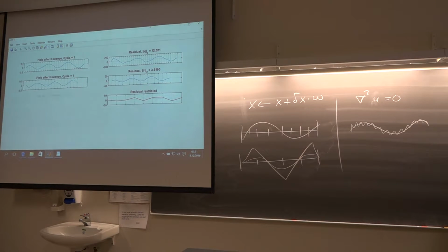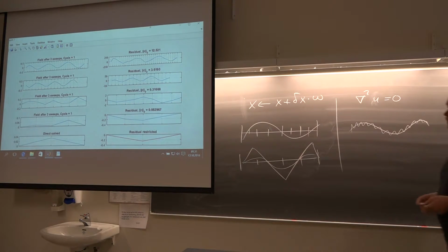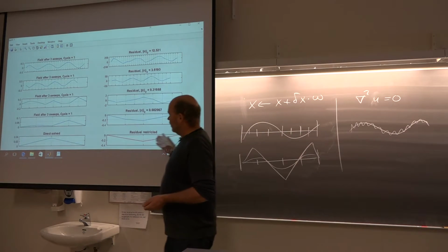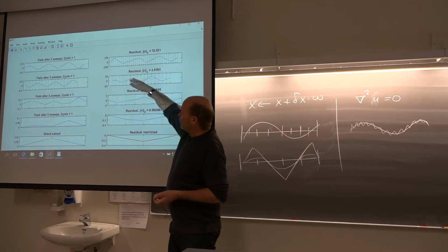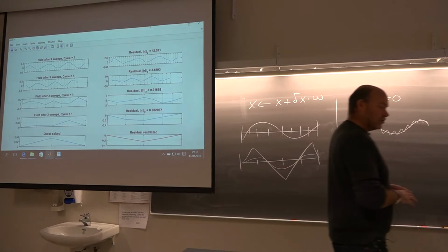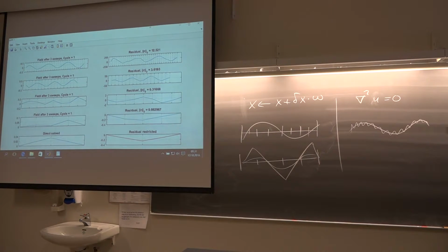Finding a residual there, doing a couple of iterations on this level, just continuing all the way down until I just have one single cell left. And here, of course, you solve the equation system directly. Somewhere along the line you have to solve it. And now I have to nest my way up again to adjust the solution that I'm interested in on the fine level. So now we go up again, adjust with the corrections that we just found, and we do a couple of iterations on the way up again as well. We had 3 on the way down, now 2 on the way up again.